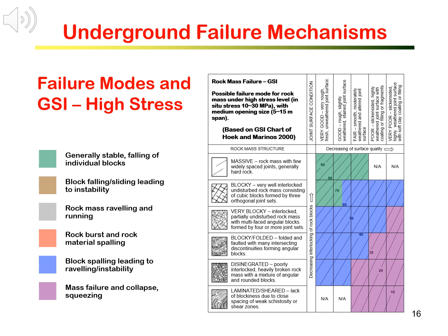For fair quality rock mass, small blocks will suffer instability under high stress. This is indicated by the large blue zone. When the stress becomes very high, more squeezing is expected for poor and even fair quality rock mass.